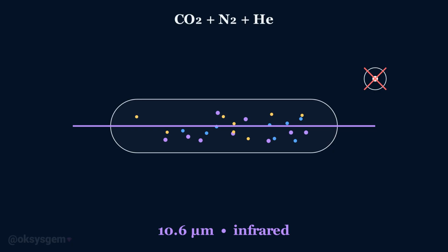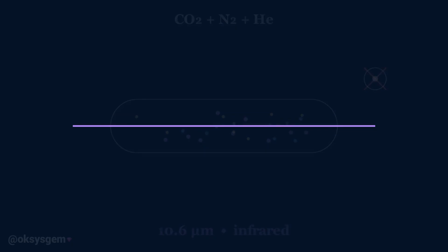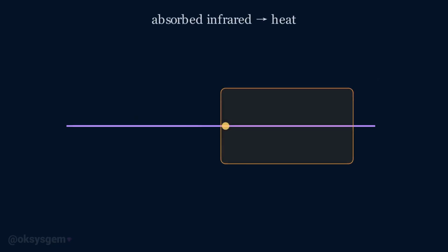However, many materials absorb this infrared radiation extremely well. When the beam is focused onto a small area, that absorbed energy becomes heat. This makes the carbon dioxide laser extremely useful for cutting, engraving, drilling, and processing materials such as wood, acrylic, fabric, paper, plastics, and some ceramics.